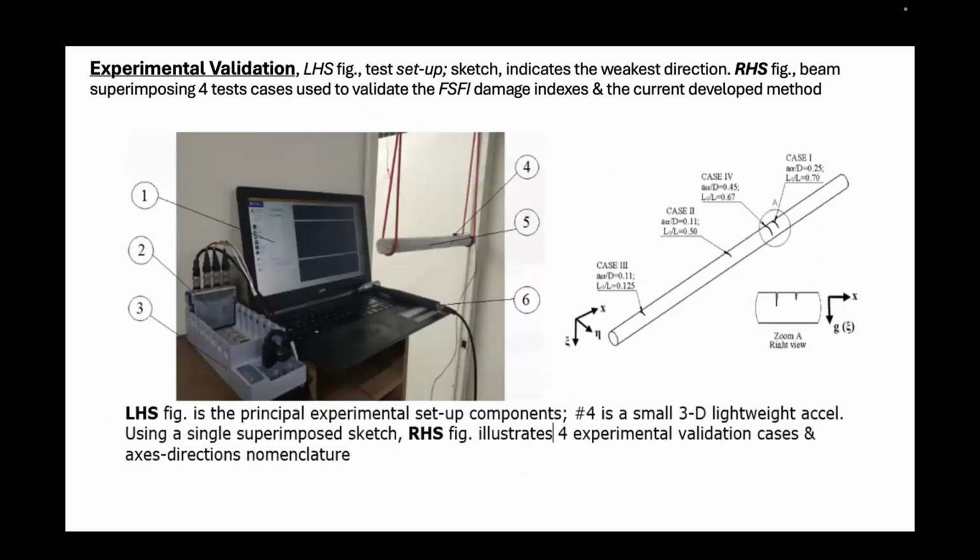Here is the experimental setup that I use. I use a free boundary condition with National Instruments data acquisition and a very bad accelerometer. The accelerometer had only 6,000 hertz, so it was not good. And I extended up to 20,000 hertz. So the more that you went beyond 6,000, the worse the data was going to be. Now I know how to use a much better one to improve the method much more.